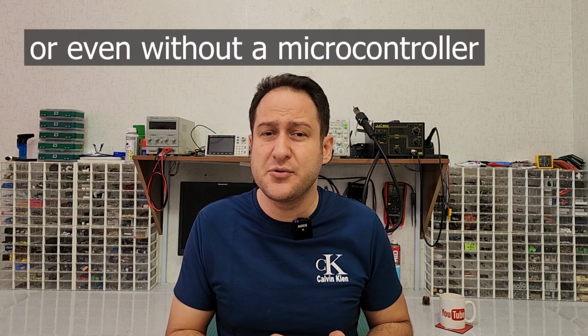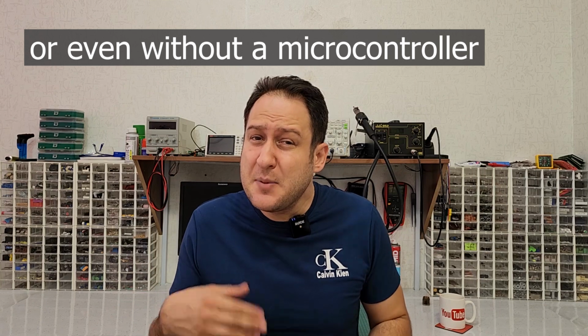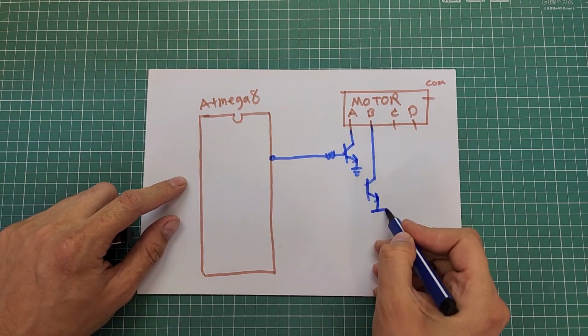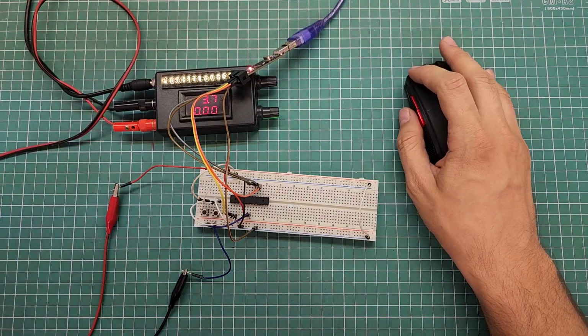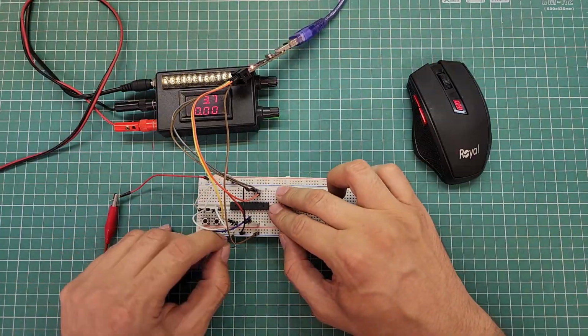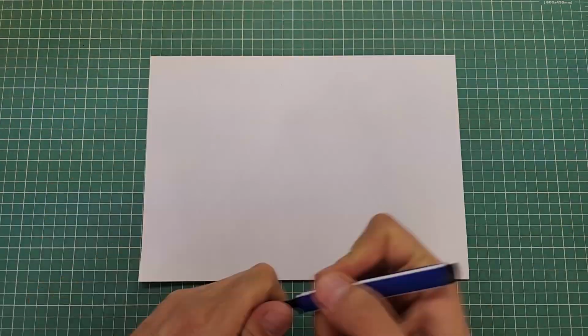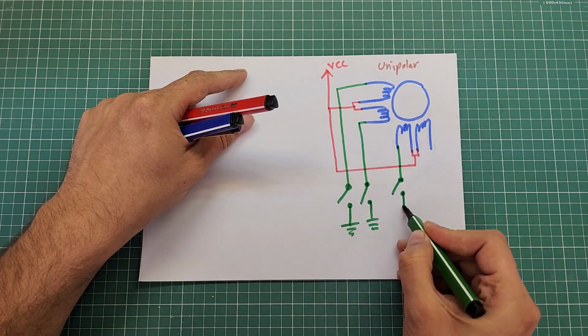Even though driving a stepper motor is not a big deal, I will explain how to drive a stepper motor in detail. You just need a microcontroller and a driving circuit. But after you succeed in driving a stepper motor, you will face a big trouble. When you run the motor at high speed, everything seems to be okay, but at low speed, the steps of motion look like the red hand of a clock, which is discrete and undesirable.